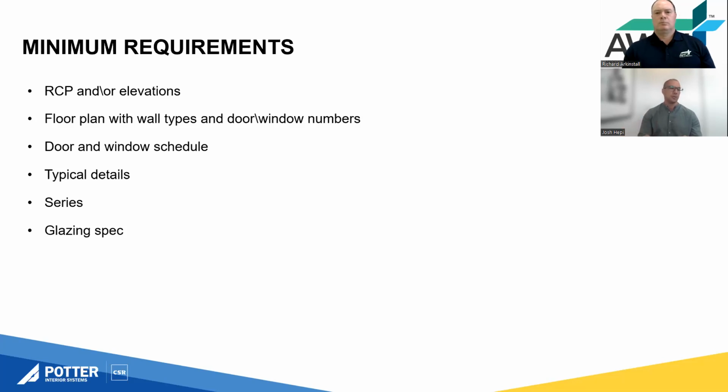What you don't want to do is come to ordering the materials, having already done a takeoff for smaller components, and then have to up spec everything. They could argue that it's at your cost for not picking that up at the takeoff stage. So the glazing spec is important where possible. Often it might just be as per the glazing code, NZS 4223, and then you just install what works, but sometimes it's all called out.